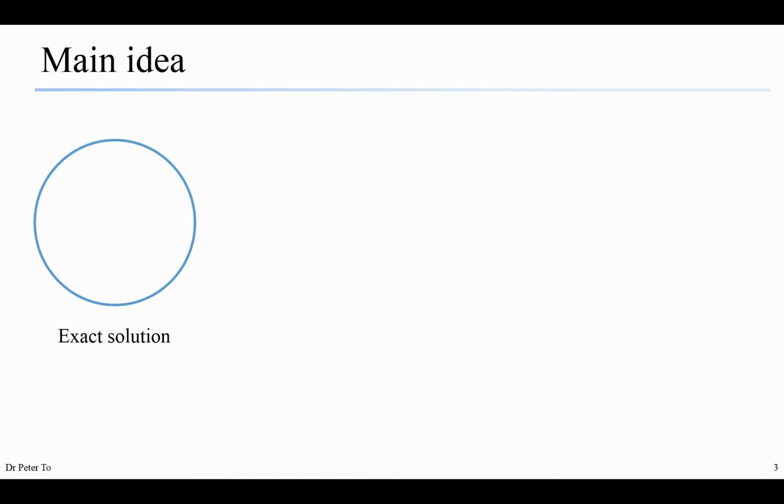In step number 4, you have to choose the element type and order for the elements. In step number 5, you have to think about the mesh density. That means you have to determine the appropriate mesh resolution. And in the final step of preparation, you have to approximate the loading conditions.